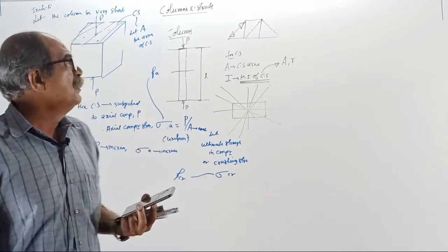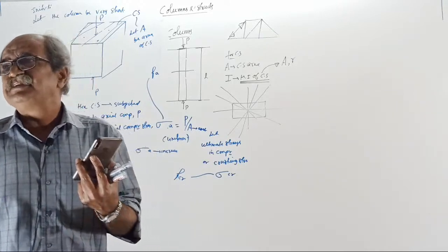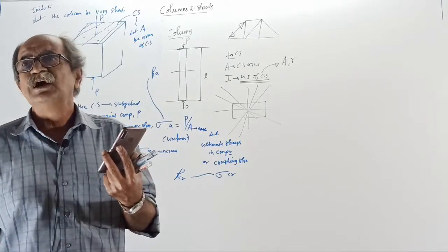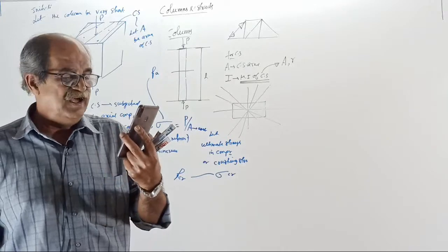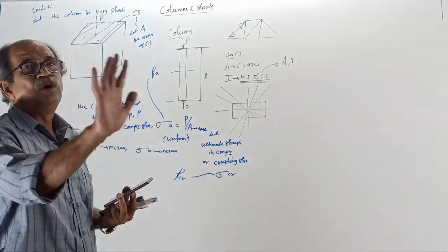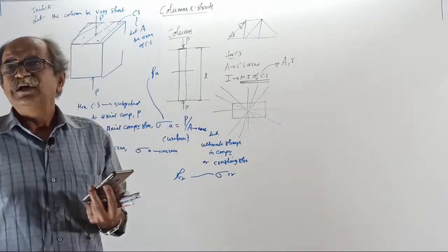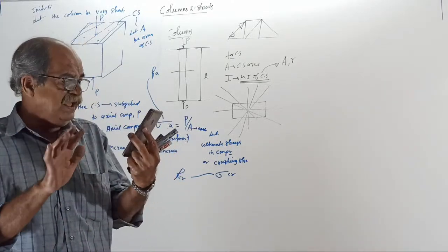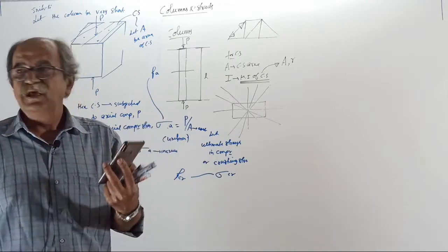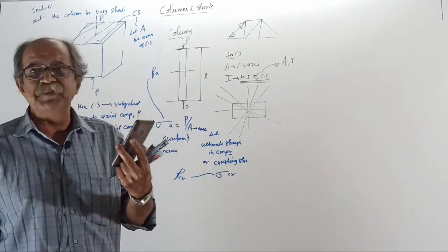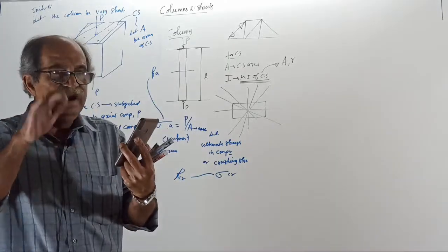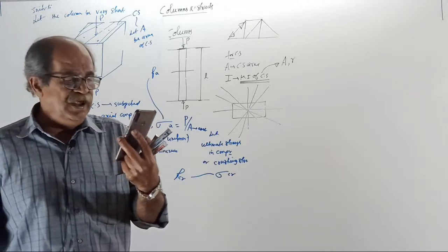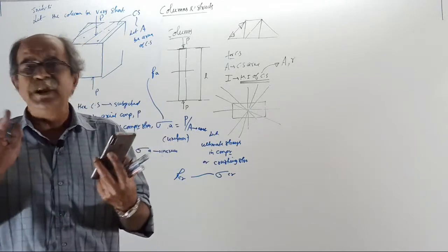Yield stress for mild steel is taken as 250. But compressive stress at crushing value is actually around 325, 330. But IS code told, don't consider it. Safe or unsafe? Even though it can take more than 300, you limit it to 250. That is all on the safer side. When IS code tells limit the strength, limit means even if you got more money, you imagine you have lesser money.